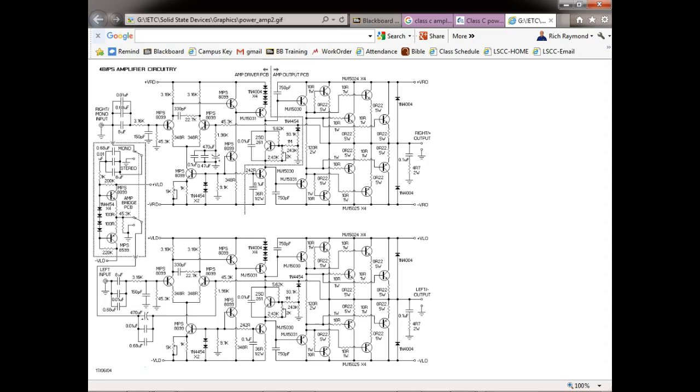You can see this is an NPN, this is a PNP, there's your Class AB, and then all this stuff down through the line here is just in there too. And we'll explain these diodes here in a minute. Down here, this would be one channel. But if you look, the two channels are mirrored. When they come in, they split your left and right channel. They are the same circuit, it's just one of them's for your right channel and one on your left channel, right?